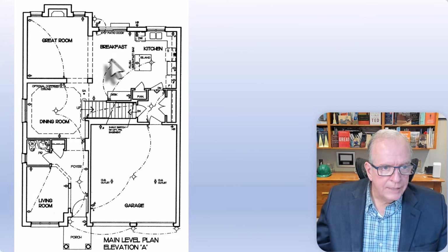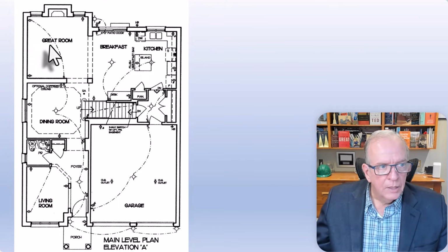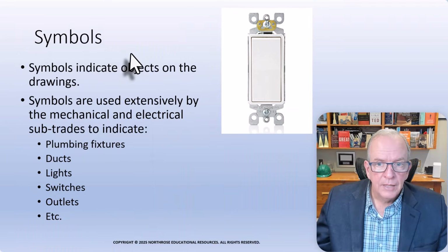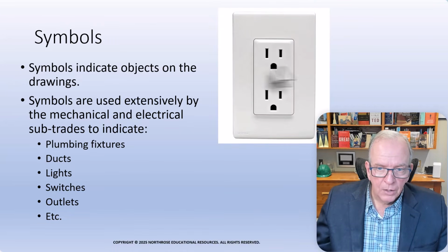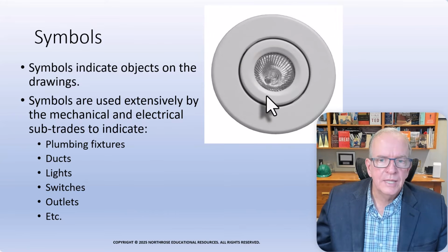So here we have a light, right? Light fixture, and that's a switch. So the S, it looks like a dollar sign or something there, but it's only got one line running through it. It just means the S, and this is the wire that's running to that outlet. So what that really means is that outlet, I'll just switch back here for a second. That outlet, the switch is operating half. All right, so it's what they call a split switch receptacle. So half is on the switch, and the other half has power all the time. So generally, unless they say otherwise, that's what that is.